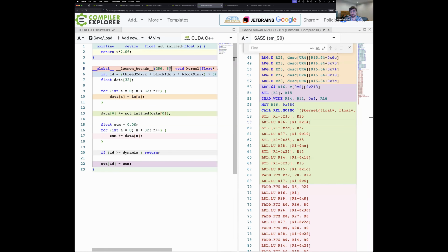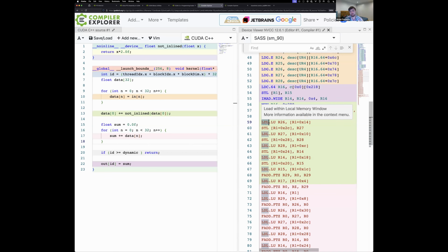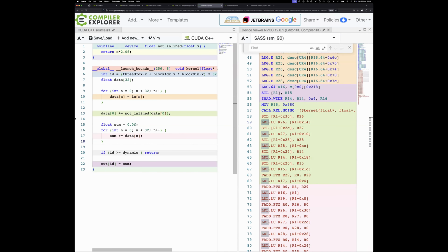So, okay, it's not forcing spilling, it's forcing compilation such that you can fit 2048 threads per SM, which means you need 32 registers or less per thread. And because of the way this shader is written, it's not able to compile below 32 registers by reordering operations. And so the compiler is forced to spill to the stack, which effectively uses DL1 and potentially DL2. That makes sense?